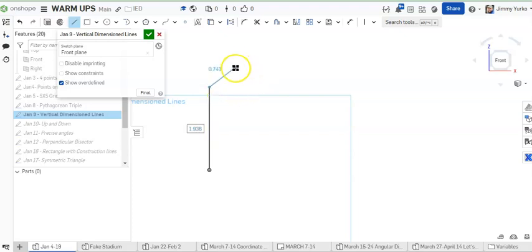At this point, you can see that if I've clicked one time, I'm going to be able to continue drawing. If I'd like to continue drawing, I can just click again. If I don't want to continue drawing, then what we can do is double click at the end of each line drawn. So here, by using the inference tool, I've hovered near the origin, brought the mouse over. I'm going to click and release, move the mouse, and then double click to set that.